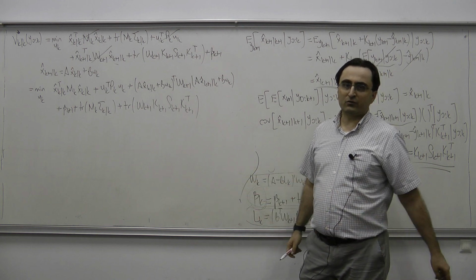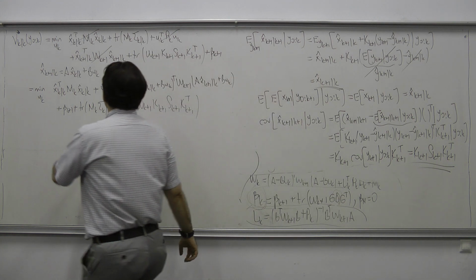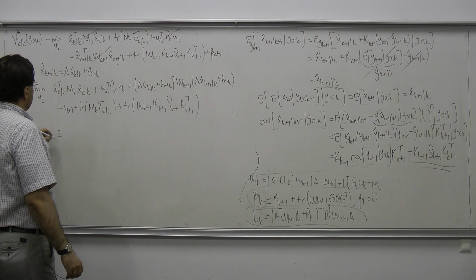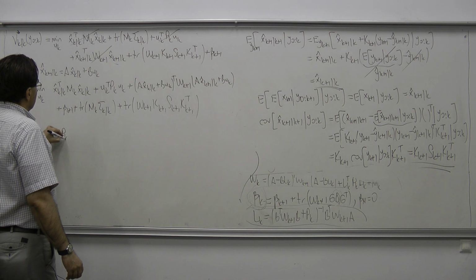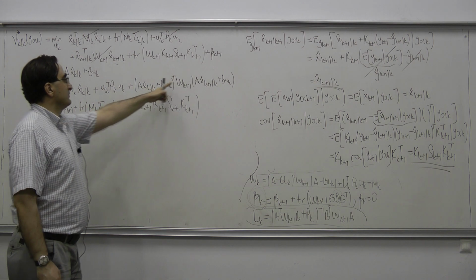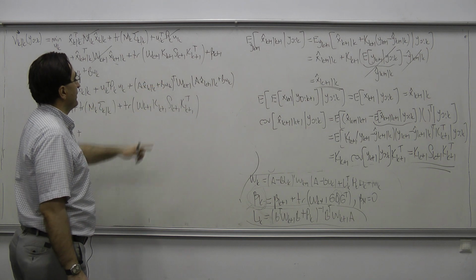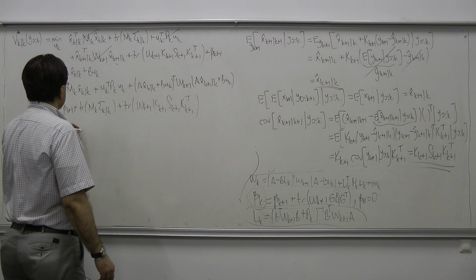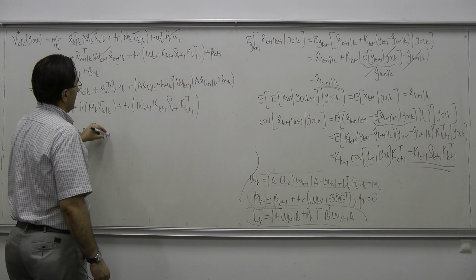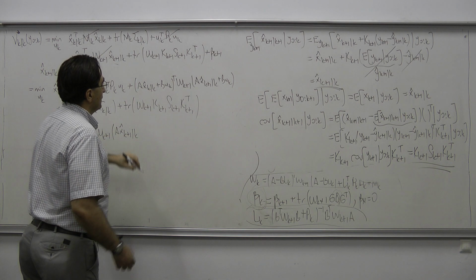Go back to that lecture and watch the similar part, and you can see that if I calculate the derivative of this term with respect to uk, then you're going to get 2 Pk times uk, plus if I take the derivative of this term with respect to uk, then I'm going to get 2 times B transpose W k plus 1 times A x hat k given k plus B uk is equal to 0.